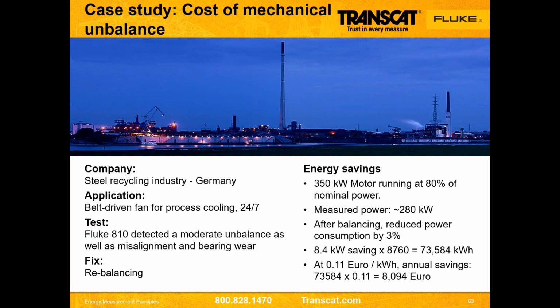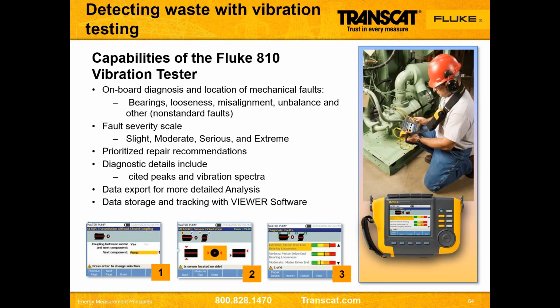So we have numerous examples of where and how these devices will pay for themselves, what we call case studies on the Fluke website. So I can find a lot of problems with the vibration tester. Right? If things are mechanically unstable because of a bearing problem, because of looseness, because of misalignment, because of unbalance, then the health of that mechanically is going to go down quickly.